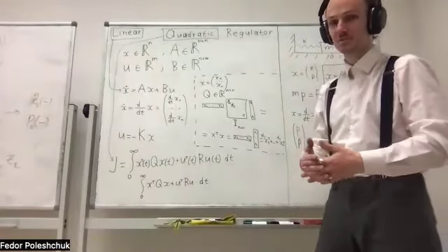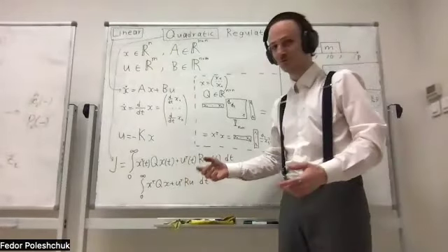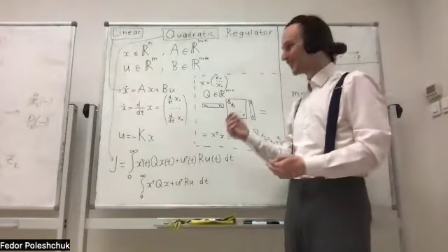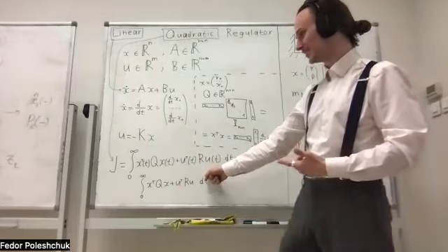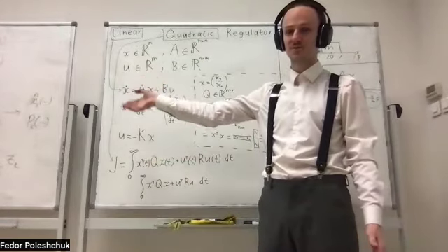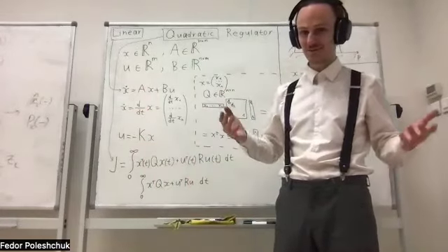And we as control engineers have to set these values for them to make sense. It doesn't make sense to set this to be an identity matrix and this to be an identity times 10 to the power of 6. It's like we're not saving effort at all. We have to balance stuff.